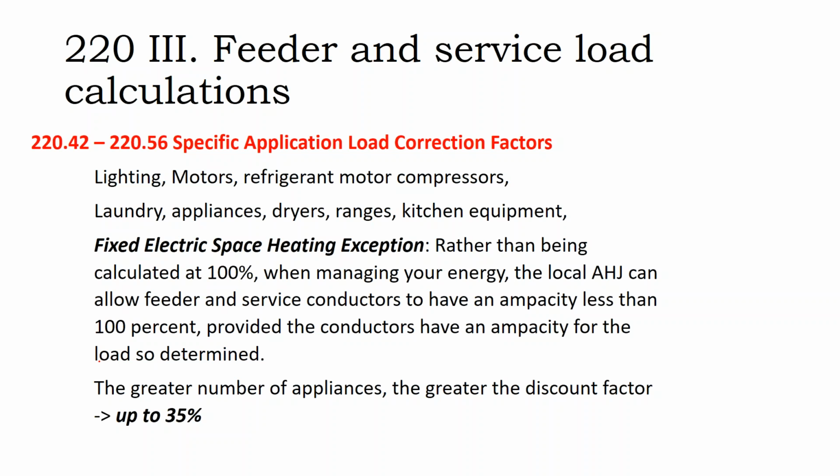And there are economies of scale when you get into multi-tenant dwellings. You don't have to assume it's like a single tenant dwelling where you have one stovetop. Not everyone cooks their dinner at the same time, and so you get discount factors as you scale up.